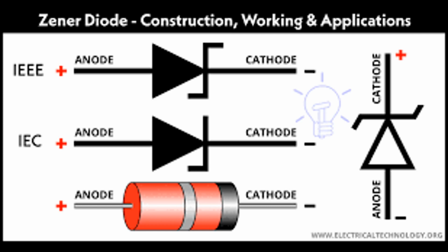Circuit configuration. A diode is placed in parallel with a resistor and capacitor, an RC network. The diode is reverse biased, and the capacitor is connected in parallel with the load, usually a resistor connected to ground. The modulated AM signal is applied to the diode's input. The diode rectifies the AM signal, allowing only the positive envelope of the modulated waveform to pass through. The resistor and capacitor, the RC network, smooth the rectified waveform to produce the envelope of the original information signal.